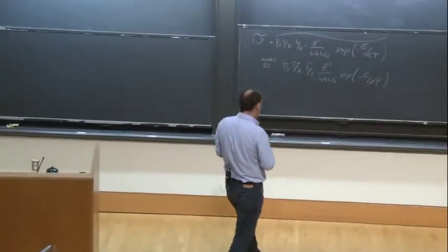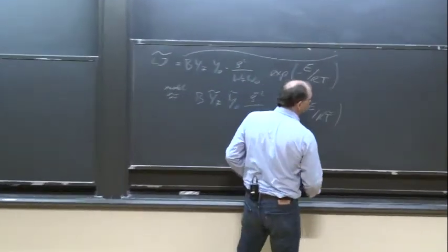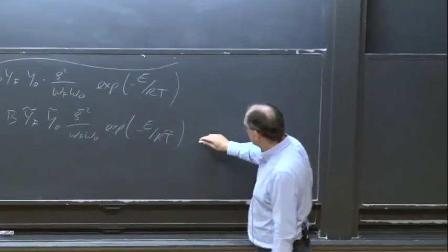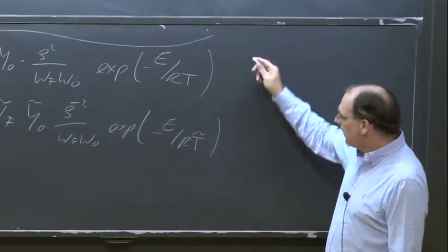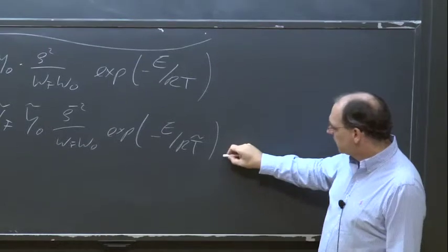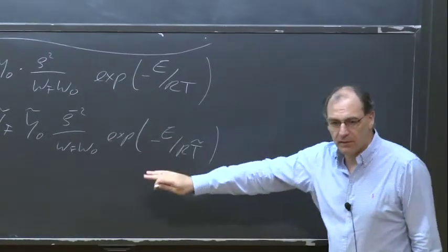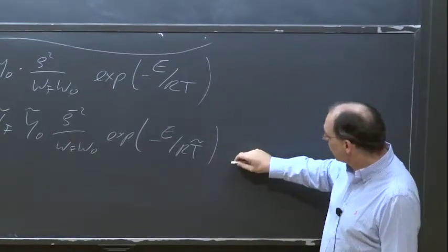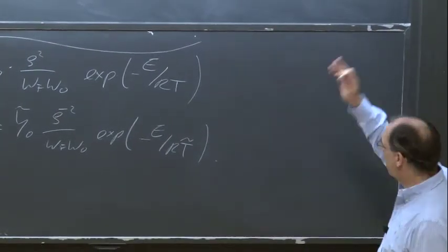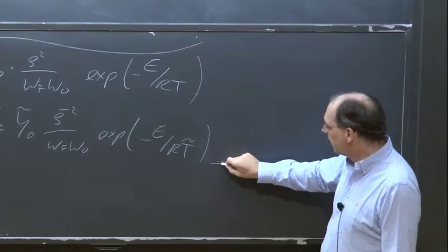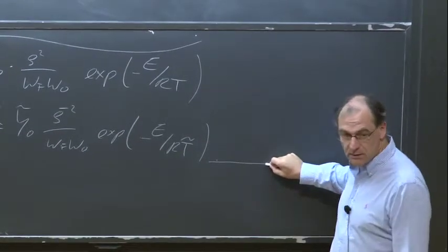What is a turbulent time scale? Epsilon over k is a turbulent time scale. Okay? So basically you could just leave it at epsilon over k, but then there would be a little problem. Here's the problem. If I look at a turbulent flame, then maybe I have turbulence everywhere, but if I'm far ahead of the flame, then the process variable, or temperature, or product mass fraction is just 0.